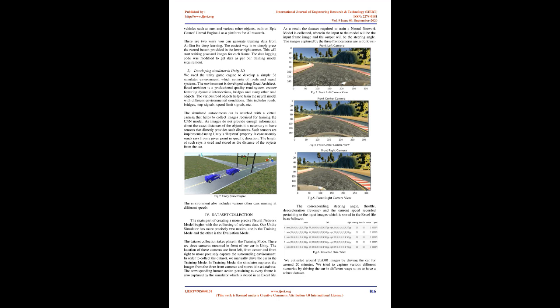We can manually drive the car in the simulated environment to collect the required data, which is stored in a local folder. After training the model on the collected data, it can be tested using the Python module. The system is based on a client-server architecture where the Python module acts as the server and the virtual car acts as a client. In autonomous driving mode, virtual camera images along with sensor data are transferred to the server. Using the received data, the model predicts the corresponding steering angle and acceleration to be applied, which is transferred to the virtual car controller.